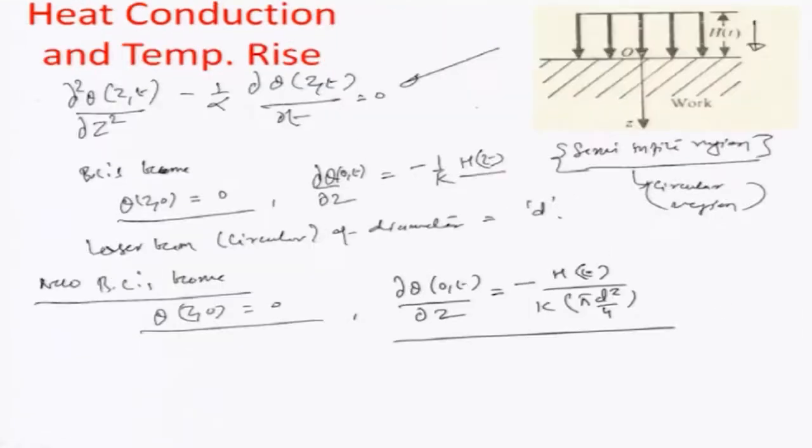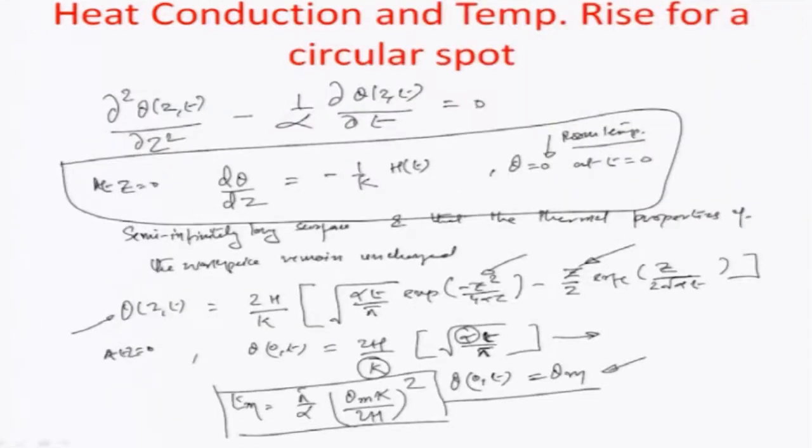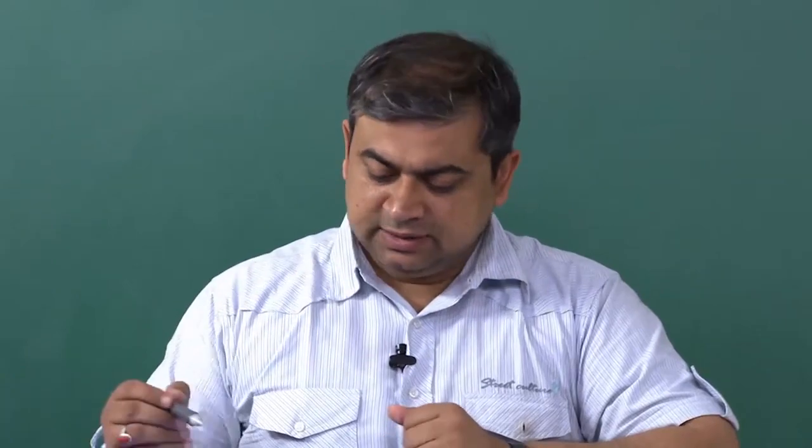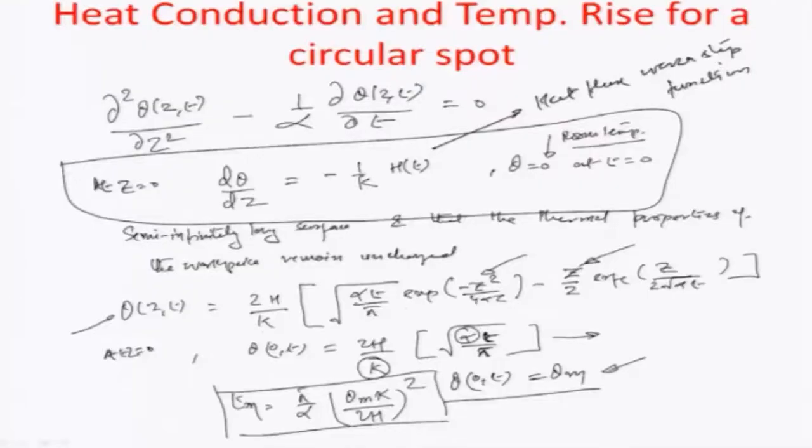If you may recall in the earlier slide as well, we had, if the heat flux were a step function, meaning thereby that we assume that the heat starts at point of time t equal to 0 with a constant heat flux h and continues therein for all points of time. So, it is like a step function. In that case, the solution that came out involved this second kind, which is basically nothing but 1 minus the error function.